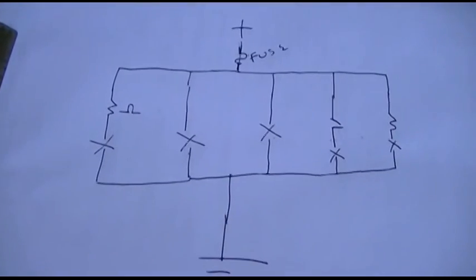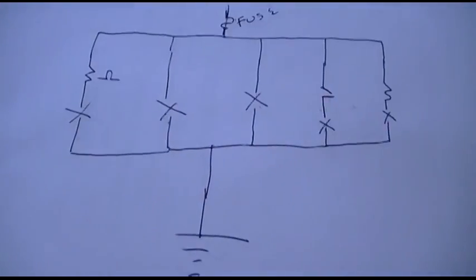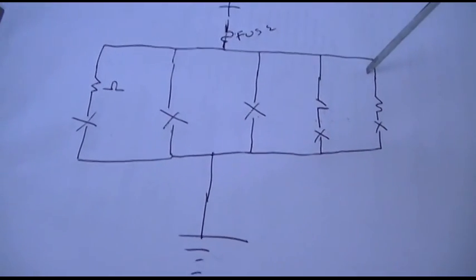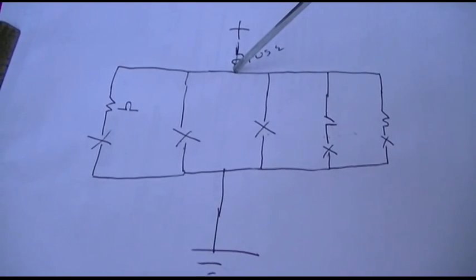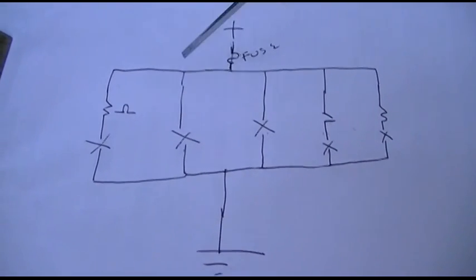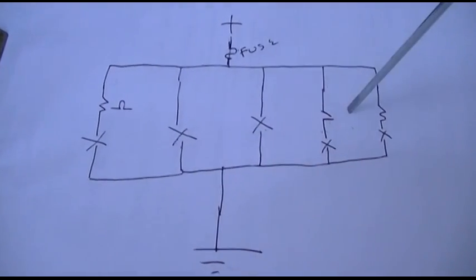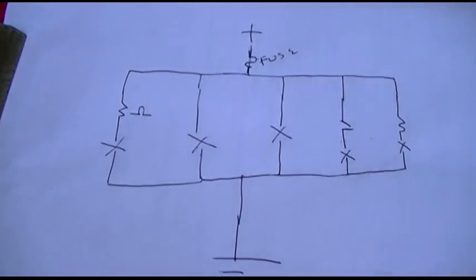Now there's a much cruder, kind of third world method that I didn't mention. Of course, the proper way is to go through and disconnect these one at a time till you find the load. The cruder way is to bypass the fuse and quickly apply power and see which one gets warm, or just bypass the fuse and see which one explodes into flames.